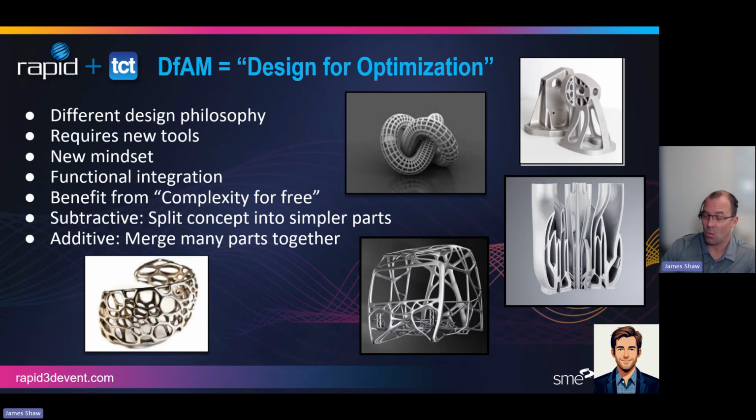So Zena just got done walking through the material aspect. We are going to change the material. If you're going to take a design of a part or an assembly and prepare it or redesign it for additive, you're going to change the alloy, right? The alloys we have for additive are different because they have to withstand this phase change and the particular process, powder bed fusion, whether we're melting it or we're starting with a powder, et cetera.